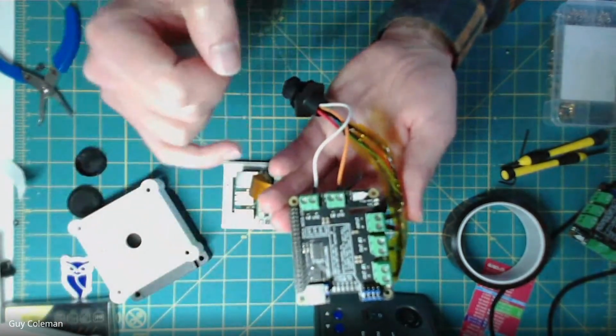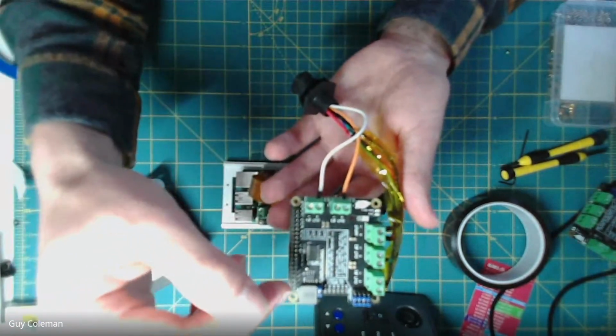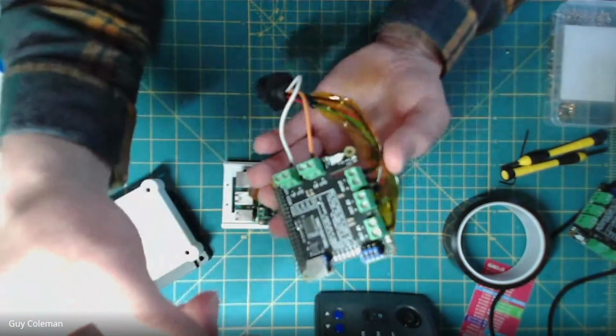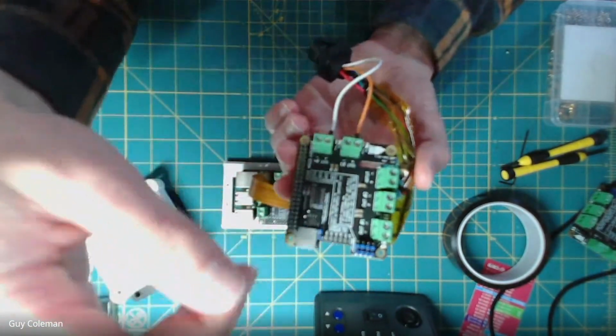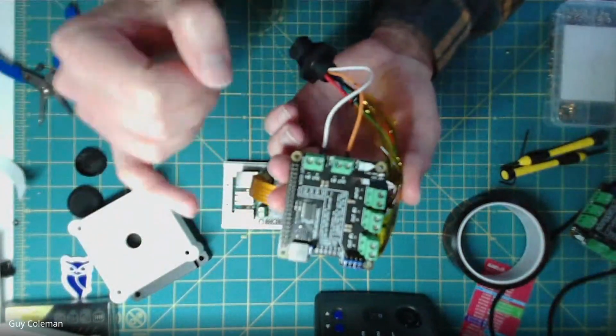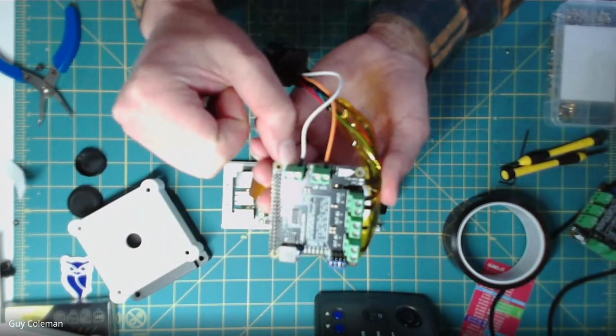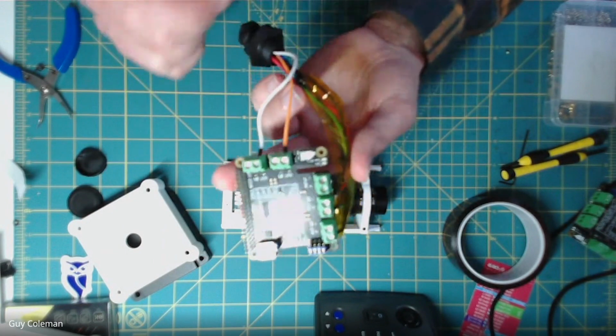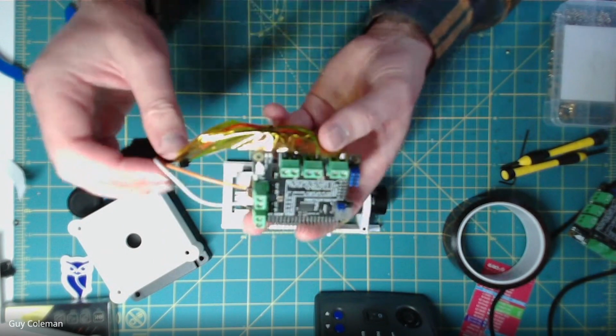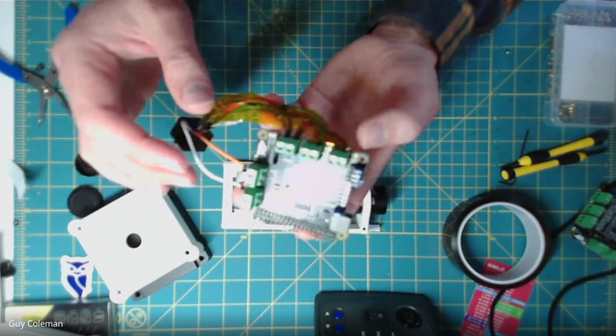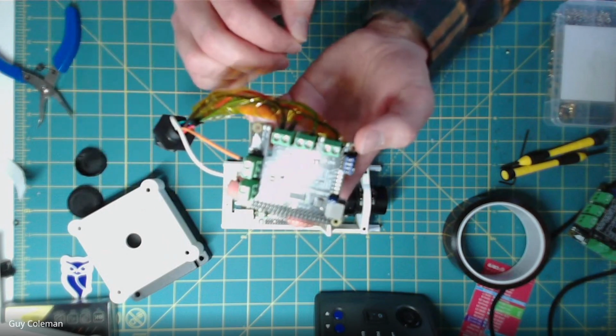So if you want to reduce the amount of heat put through the board, I guess if you're using 4 2-amp solenoids, then that can sort of generate a lot of heat inside the board. So potentially you can add a ground or your own earth pin out here and then connect it up, which I have done in the past. But this is a little bit neater, and it's not often that all 4 solenoids are on.